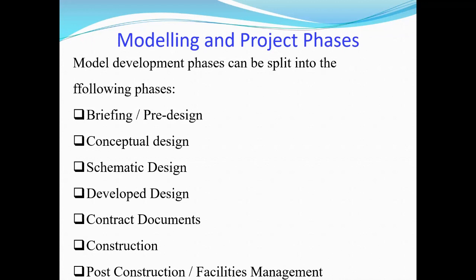At that time, the engineer decides what structural scheme to use. We have a lot of schemes: one-way beam slab, two-way beam slab, flat plates, portal frames and beams, and so on. At that stage the engineer decides which scheme is suitable for this building, and whether to use shallow foundation or deep foundation. That's called schematic design. It's still geometry, not detail.